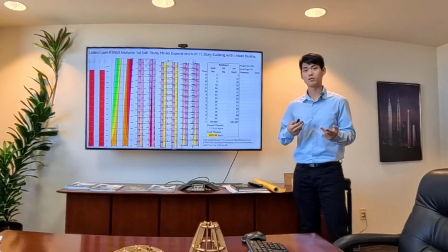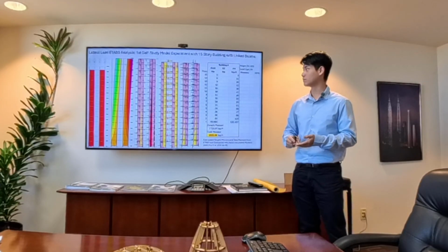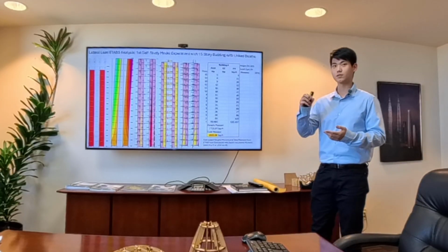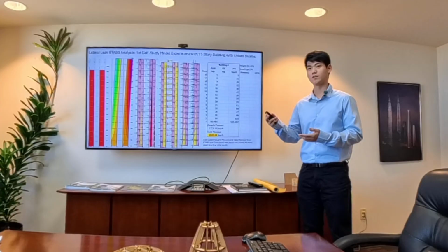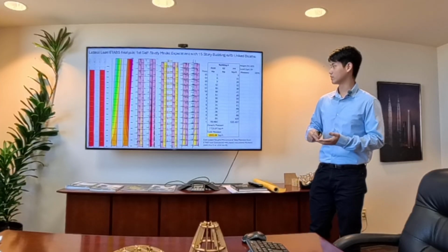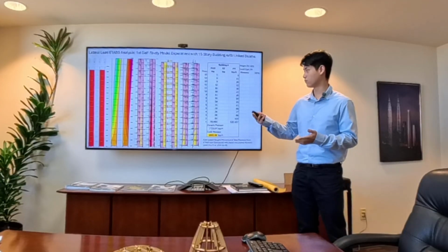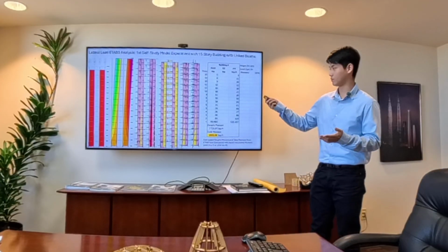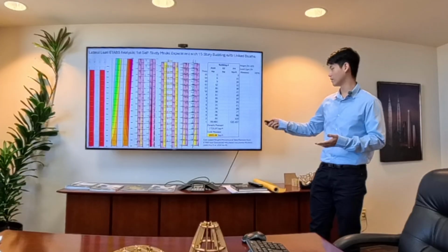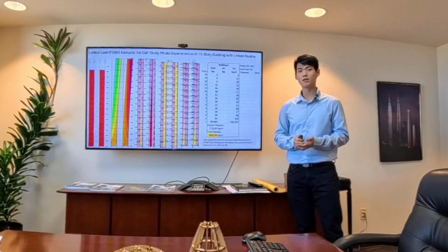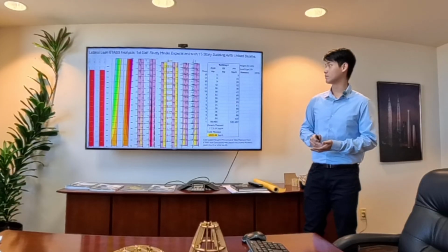This was a self-study model. I modeled only 15 stories, and I assigned the piers and added the labels to be able to analyze the effect of the lateral reinforcement that coupling moments or the link beams can provide. And same thing, I calculated the coupling moments and total moments and compared the ETABS values with mine.